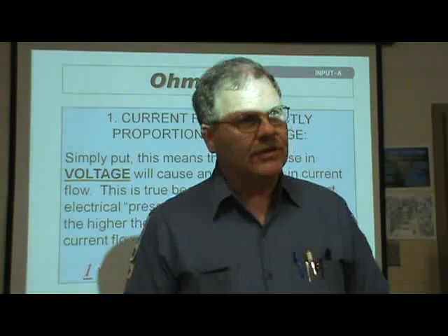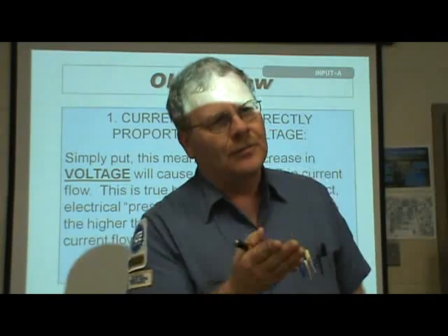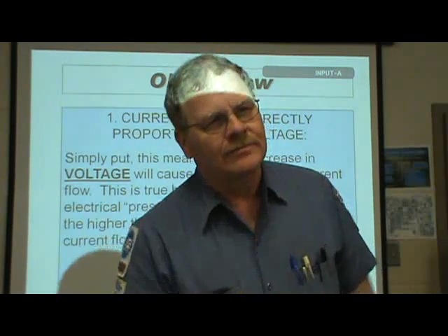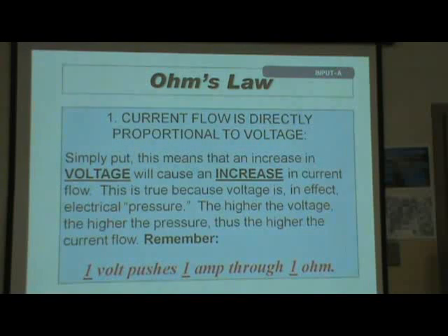Higher, yeah, the higher voltage. You're only going to use half as many amps with a unit that's made to run on 220. Got it? Because you've got twice as much voltage, and it takes half as much amperage to do the work because of the extra push. You see where I'm going with that?